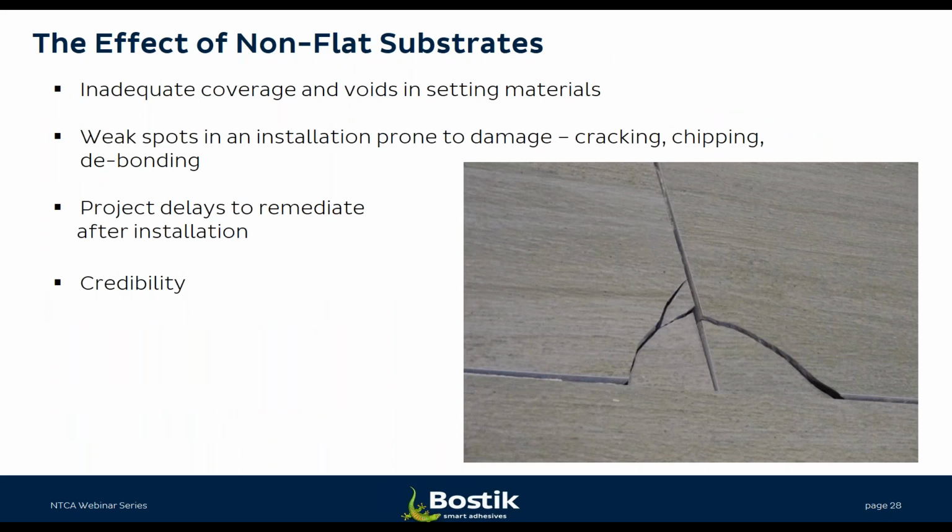So flattened substrates is really a total requirement for protecting a finished installation and making sure that installations don't have weak spots behind the tile installation that could result in cracked tiles or debonding, cracking, chipping, and a variety of other types of failures. This could also result in project delays to remediate after the installation. It could be a credibility ding. So adequate coverage and no voids in the setting materials and surface prep is essential to the success of these types of programs.